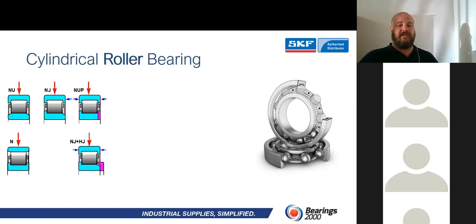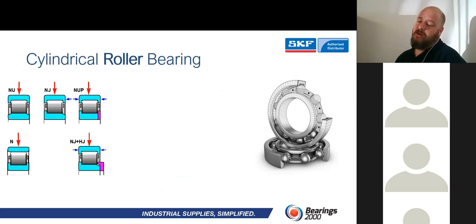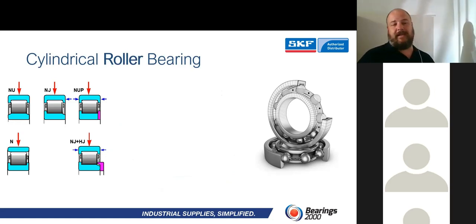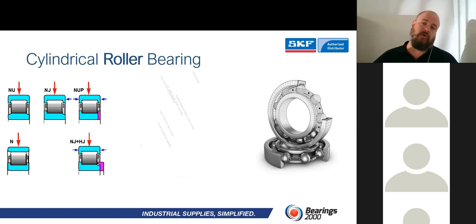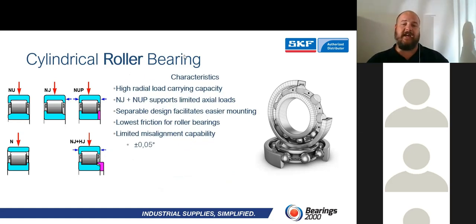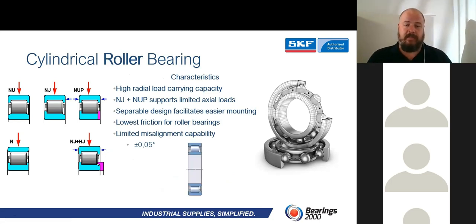Good. Cylindrical roller bearing. That is the oldest of the roller bearings, and that is just made for red arrows. That is radial load all day long. Always your located unit, as the bearing itself does the work in terms of thermal expansion. So you need to be able to, if we have a look at it there, that is what the bearing does. It moves within itself. So you need to locate this unit so that it is able to perform as it is designed to perform.